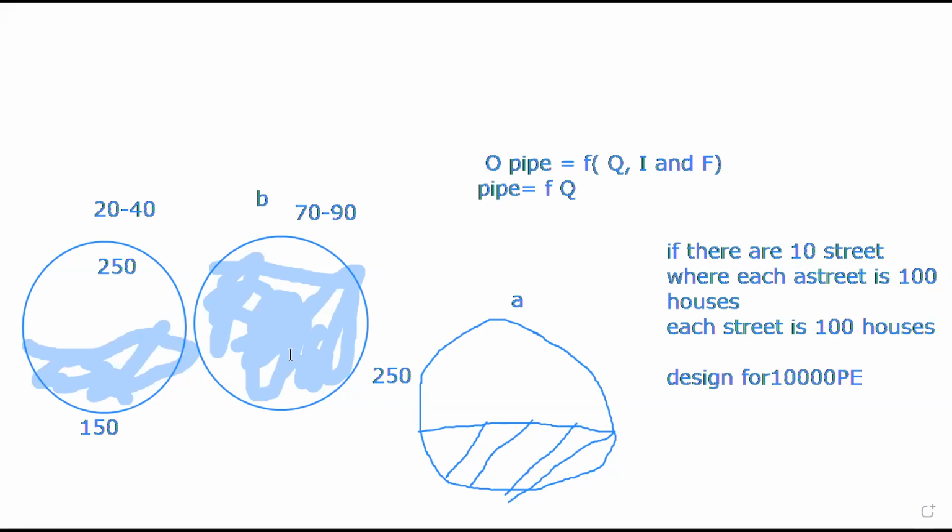Because the implication is that if this 250 mm pipe will cost 8,000 per meter length, and you now want to use it here, whereas this one, that's 150, should cost like 4,000 per meter length. You can see that, and everything is about the pipe. If you talk about water reticulation design, if you calculate the pipe, you've got 70% of the total cost of the project.